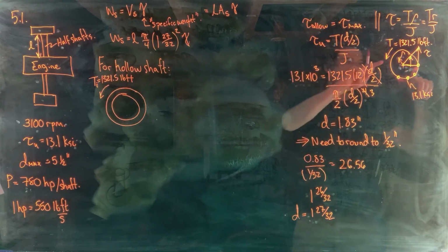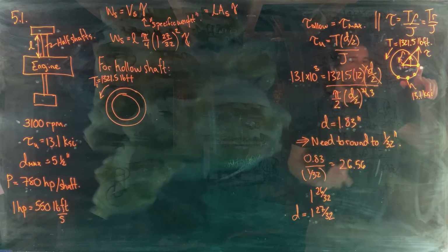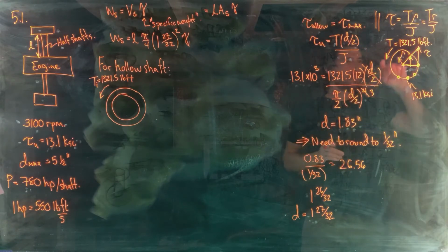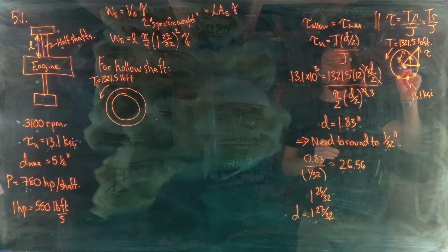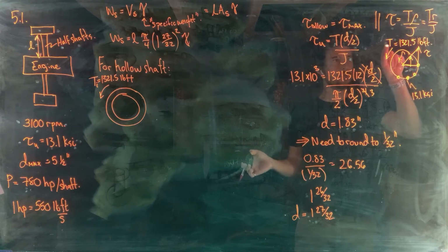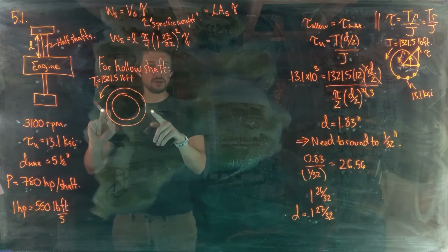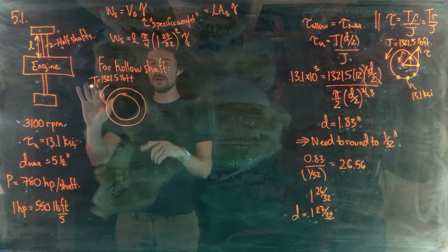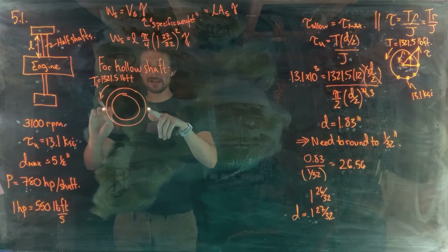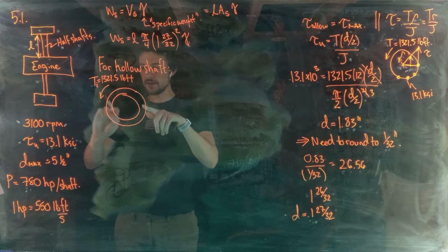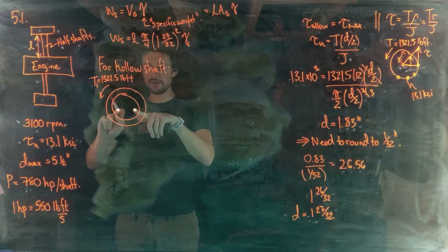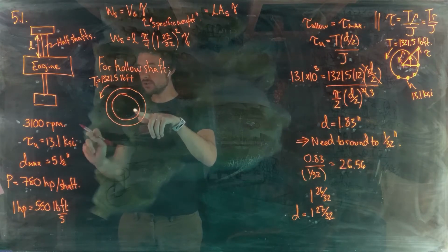We know that, again, shear stress increases going outwards from the center. The material along the circumference, therefore, carries more of the torque that's being applied than the material in the center. The material in the center is under zero shear stress, so it actually doesn't contribute to resisting this torque. So if you want to design a hollow shaft most efficiently, that is with a minimum amount of material to carry an applied torque, you want to maximize your external diameter and then figure out what your internal diameter needs to be to meet your stress requirement.